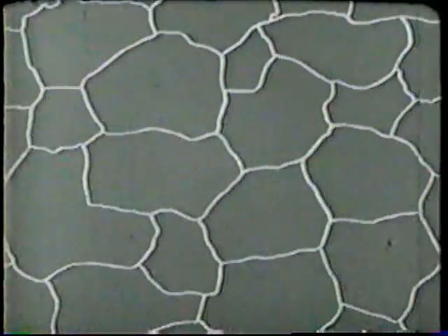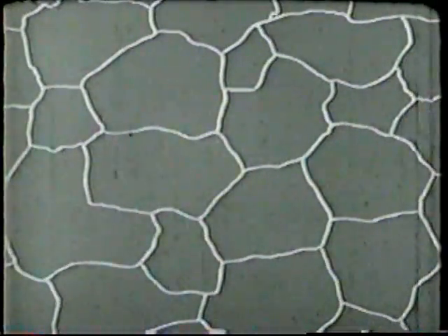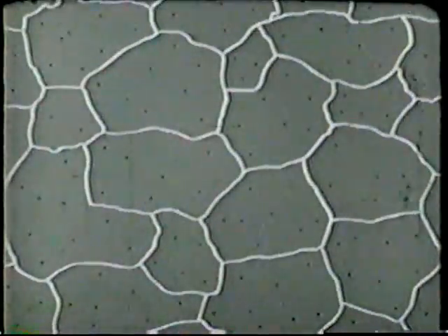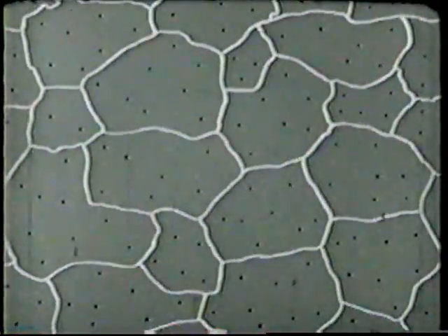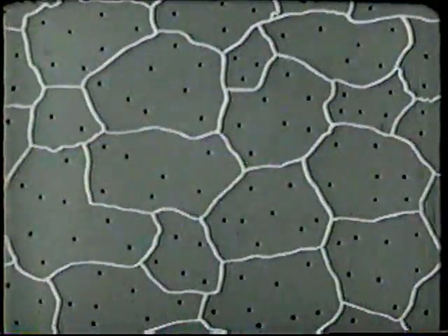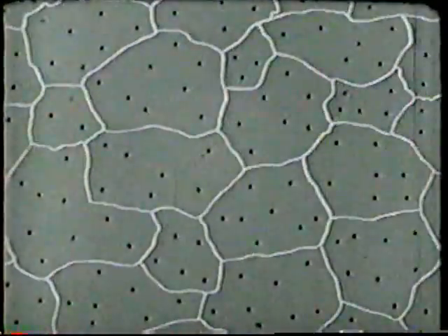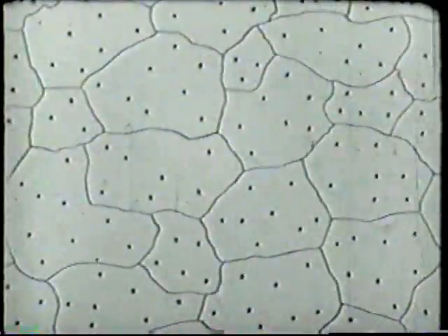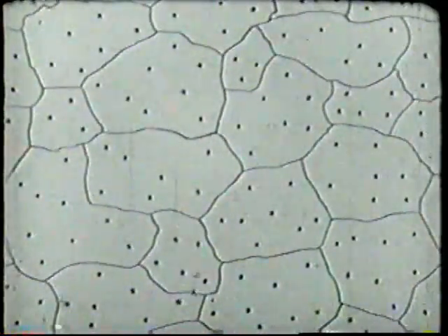The first internal change in the partial annealing is a relief of the cold work stressed grains and the recrystallization of the metal into new stress-free grains. The second change, resulting in partial removal of the effects of heat treatment, is the partial precipitation of the CuAl2 particles out of solution throughout the newly formed grains. The quench prevents this precipitation from becoming complete.